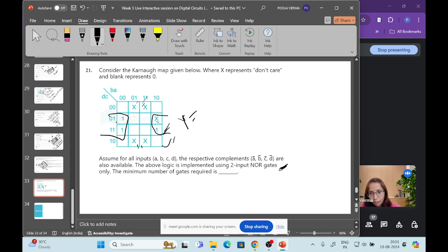So here, what is the common? C. And for these columns, what can we take common? A, right? From this, 0 will be common. Here A is written in the opposite direction. Just remember, here it is not given. DC means D this value, C this value. Here B this value, A this value, right? Always see which sequence it is given. Okay, so that means this represents the A bar, right? So what will be the expression? A bar C, right? For this K map.